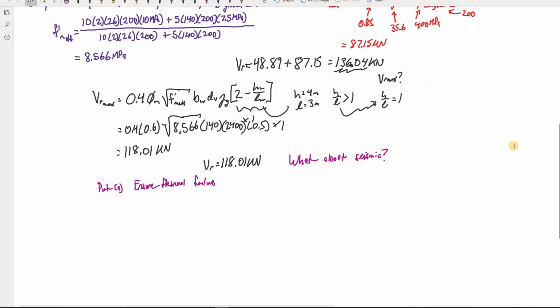And so if I go through and do this, I'm just going to save you some time. But basically, what lateral load would cause that? I'm just going to write VF seismic, and I'm going to put in brackets A because there's another requirement we're going to check. But basically, it's equal to that VF initial multiplied by the ratio, or basically how far our moment resistance is over our factored moment.